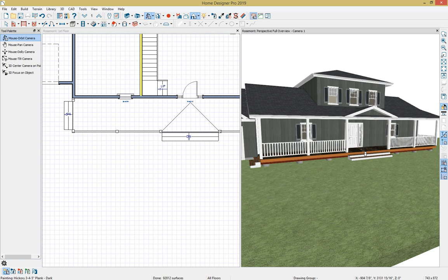And now, one thing I would like to note is that there are 5 different material painter modes that you can use. If you look at the bottom left-hand side of your screen, you can see these. So these allow me to replace the material per a component, or I can replace the material on an entire object, replace all like materials for the room, the floor, or the plan.